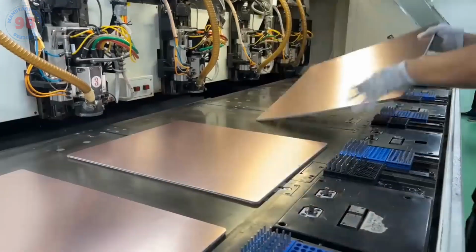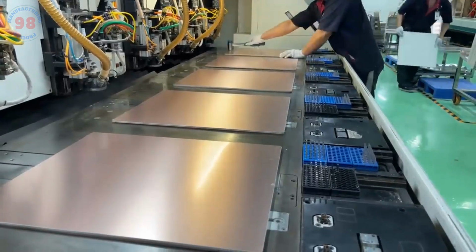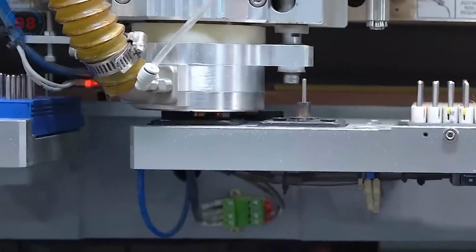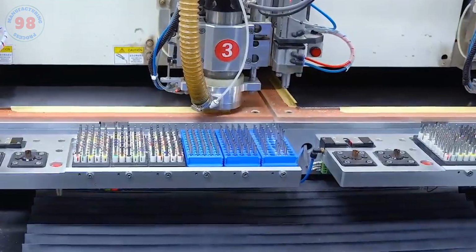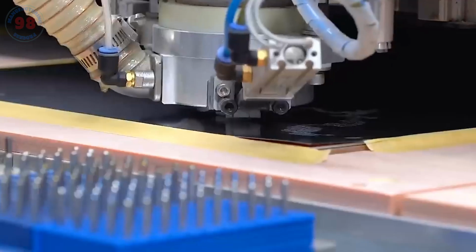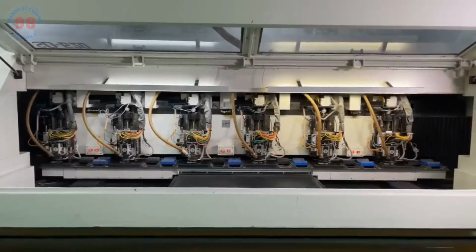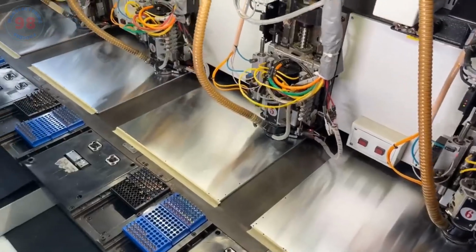To begin the electronic circuit manufacturing process, copper-clad plates are first fixed on precisely programmed drilling machines. Based on data from engineers' printed circuit design and simulation software, the drill will automatically select the appropriate drill bit to drill component holes on the copper plate. Thanks to that, drill holes are created with high precision.